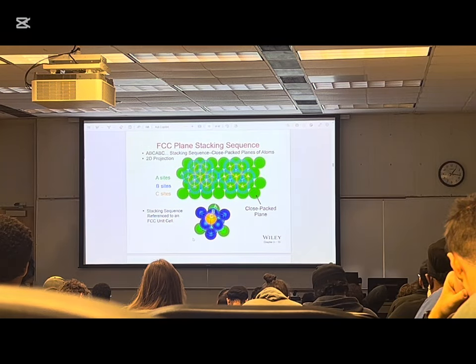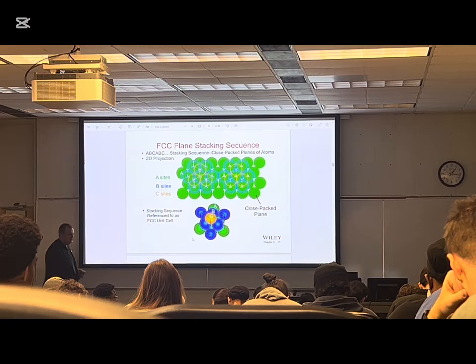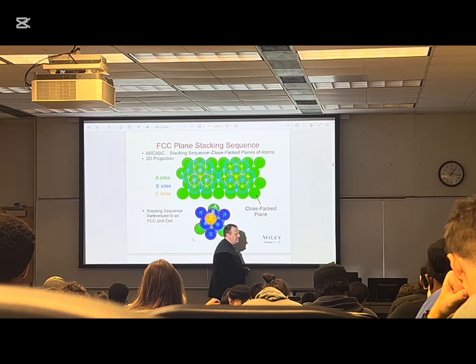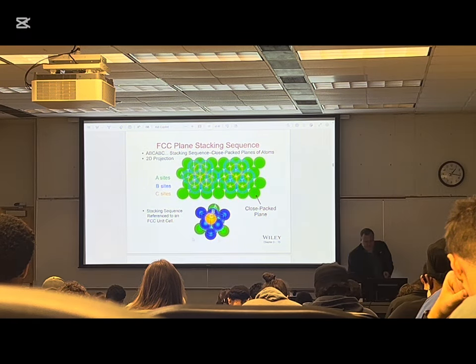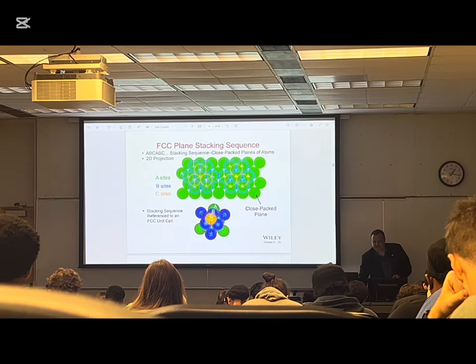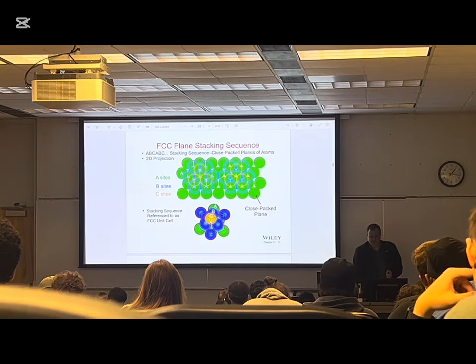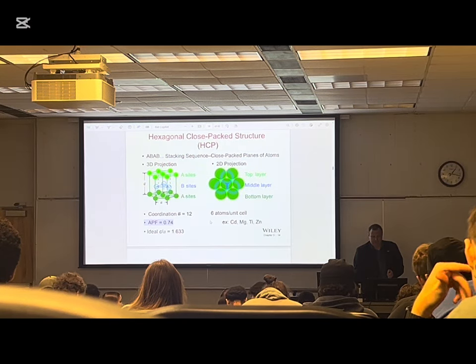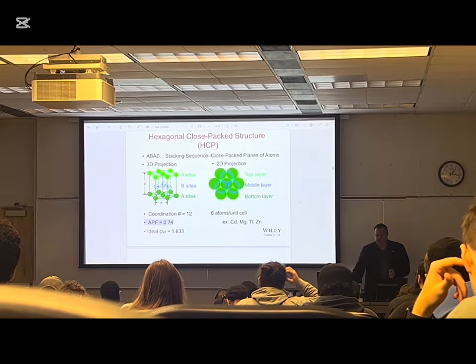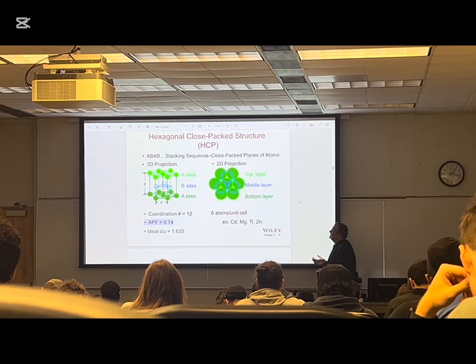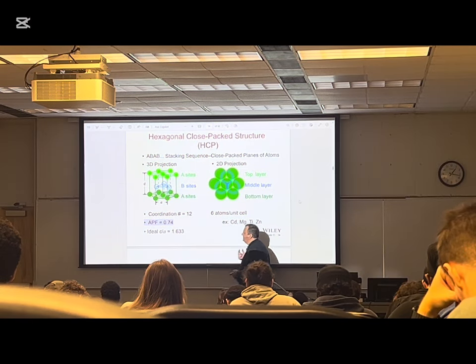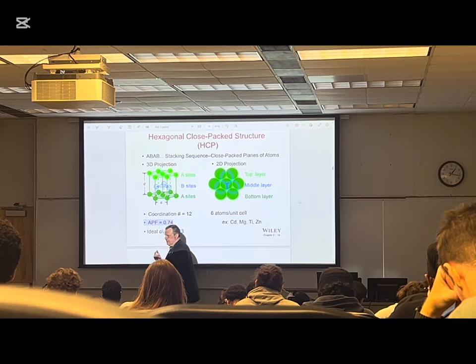By the way, it's called hexagonal close packed. I didn't get to that yet. So you can see for the stacking of ABC, it's the diagonal of a face. And I gave you the H so you can actually see it. But for ABA, it's called hexagonal close packed, HCP.